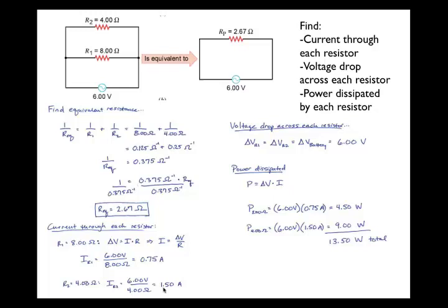The way I think about it is this. The energy difference across each of those resistors in a parallel arrangement is the same. So each of the charges that enters the resistor is going to be carrying the same amount of electric potential energy, but more of those charges are going to go through the 4 ohm resistor, and it is going to end up dissipating more total energy because more charges end up flowing through that path.